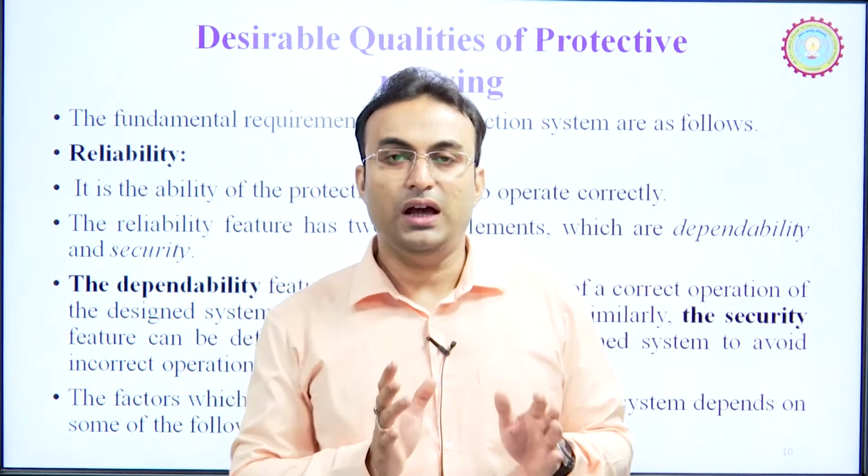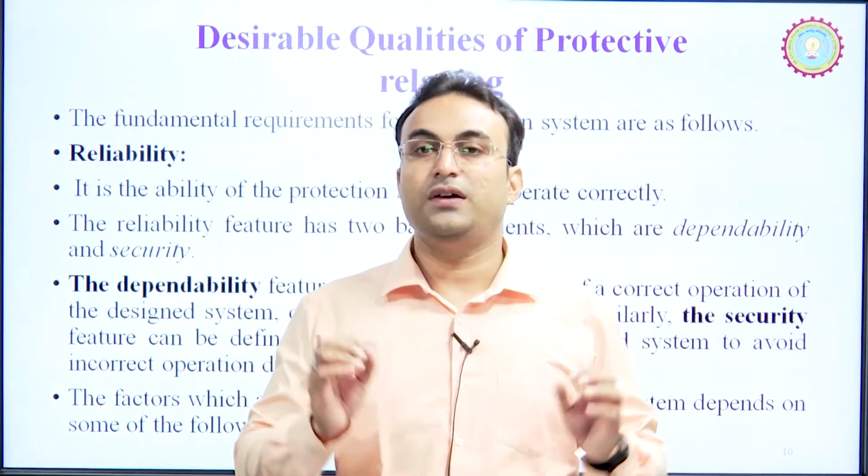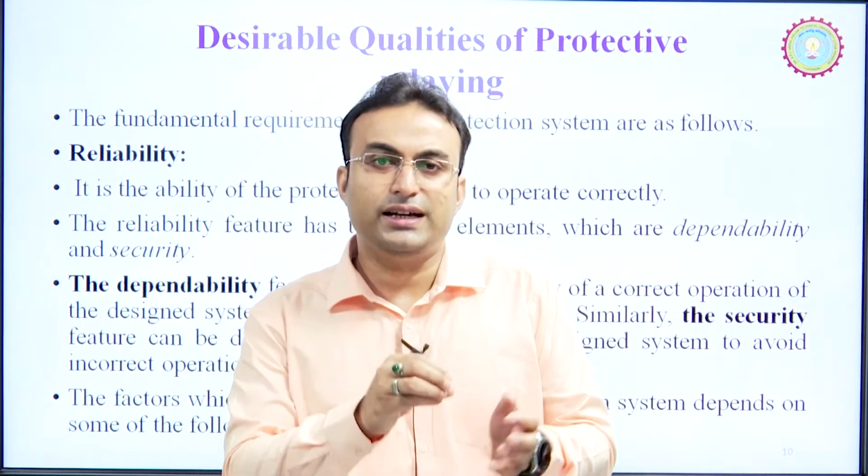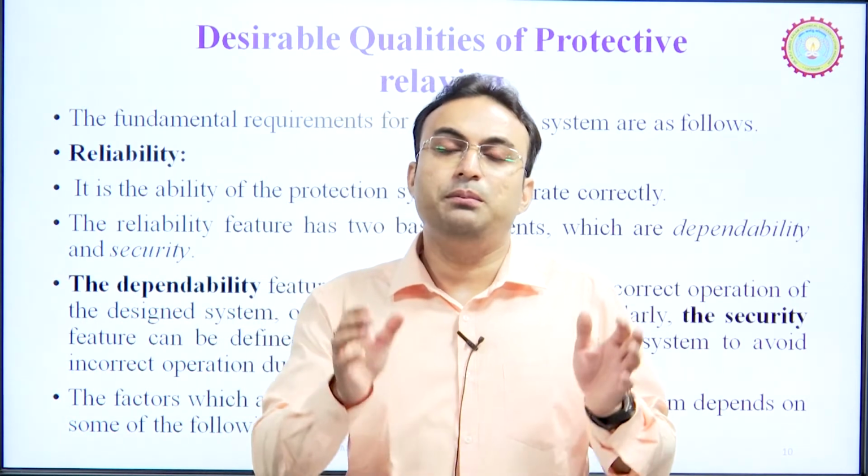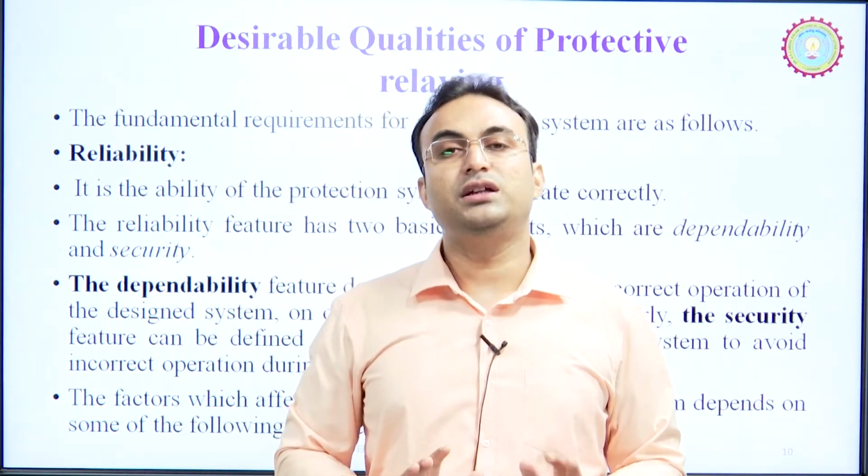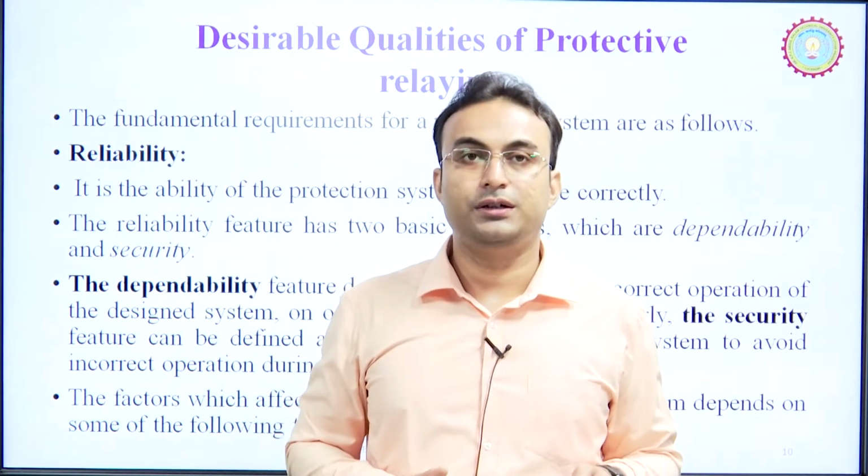No, we have some selectivity. We have some decisions, so that if a fault occurs in a section, we want the minimum number of circuit breakers to operate. We don't want all the circuit breakers to operate.